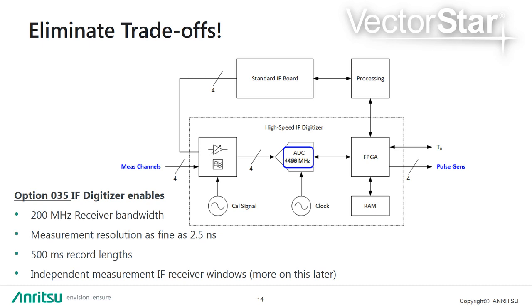The exact acquisition method differs in that the acquisition itself is not controlled by the pulse system, except in the case of pulse-to-pulse measurements. Portions of the data can be recorded to be analysed and correlated with the pulse pattern being used, and this enables the ability to have independent receivers, which we'll talk about later. Since no energy is being discarded in the high-speed digitizer pulse measurement method, there is no duty cycle dependence, and full dynamic range is now available.